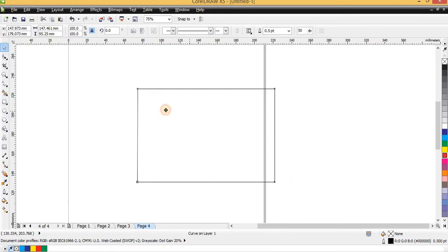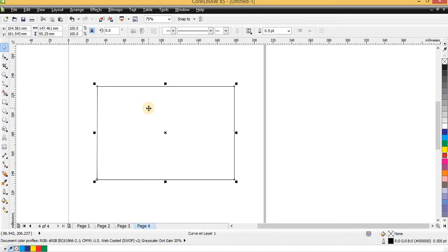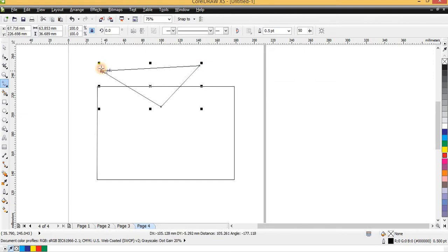So in other words, one thing you want to achieve could be done in many ways. All that will matter to you is which method is most convenient for you to use. So I was trying to get this, and that is how it is. But if you draw without holding Shift, the line might not be perfectly straight. Doesn't mean that you cannot use your eye to look at it, but you can just click any way you want to click. And then if you want to continue from there, you have to come back and click on the last point you stopped and double click. This time around I'm forming a triangle out of it. So that's the way the freehand tool works.